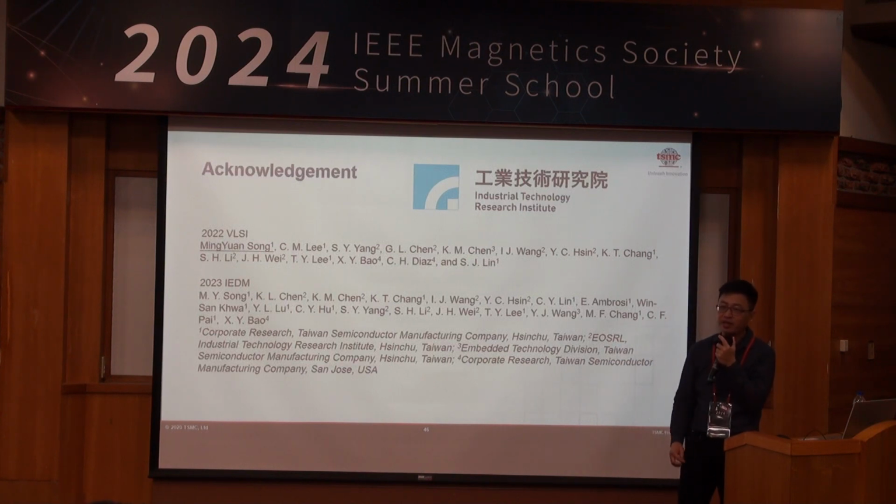That's a good question. At the very beginning, like most people, we worked on improving the spin-Hall angle, but in the end we found that the spin-Hall conductivity is more critical. So nowadays we don't pursue a high spin-Hall angle anymore. We pursue a high spin-Hall conductivity, because we also want to reduce the shunting current.